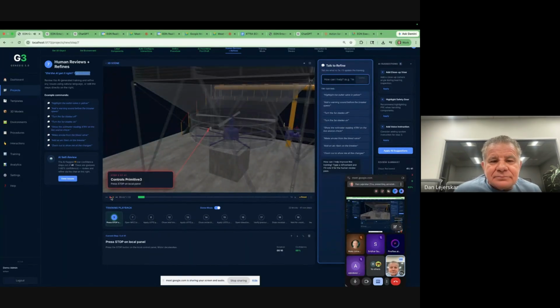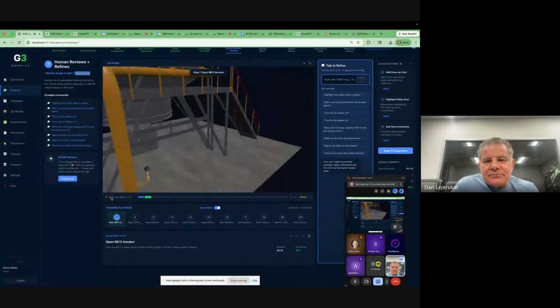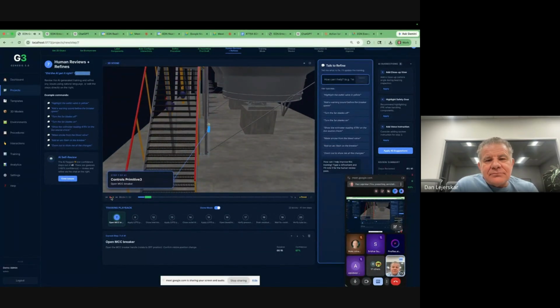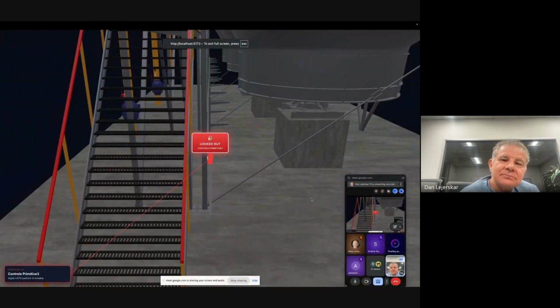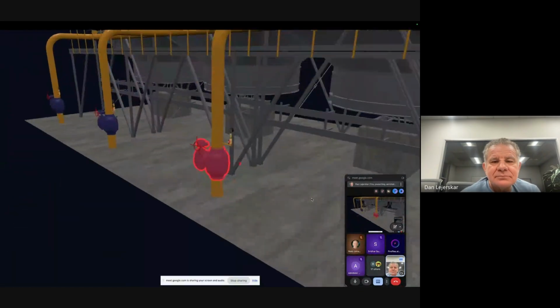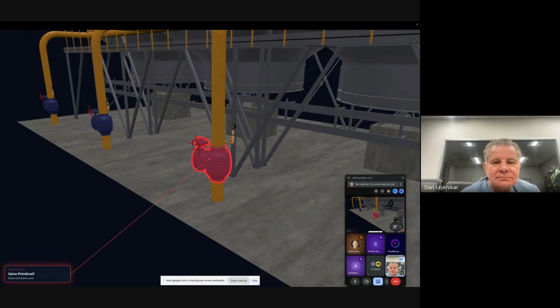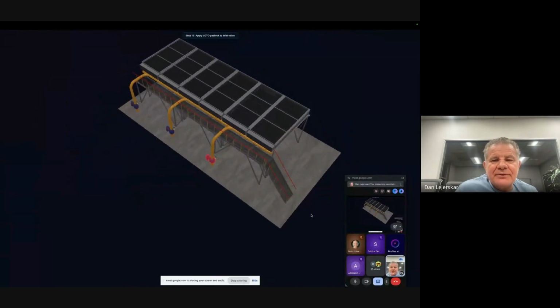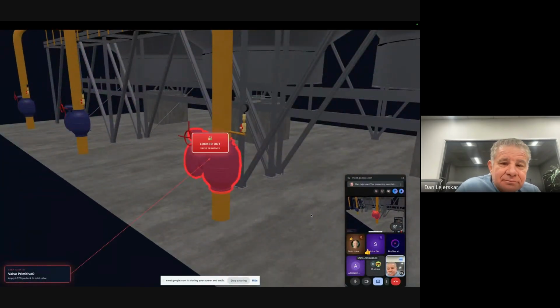Verify work permit, verify equipment tag, don PPE, notify control room, press stop on local panel. Walk to motor control center, open MCC breaker. Apply LOTO padlock to breaker. Attach danger tag. Verify 0 voltage at motor terminal box. Re-verify voltmeter on known live source. Close inlet block valve. And I can manipulate here while it's doing it. Apply LOTO padlock to inlet valve.